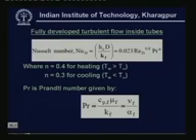This is a very popular empirical correlation, very widely used, as I said, for fully developed turbulent flows inside the tubes. And if you are using a hydraulic diameter, you can also use this for non-circular tubes. But this is again valid for a certain Reynolds number range, and also for a certain Prandtl number range. So, when you are using this equation, you must know the range under which it can be used.